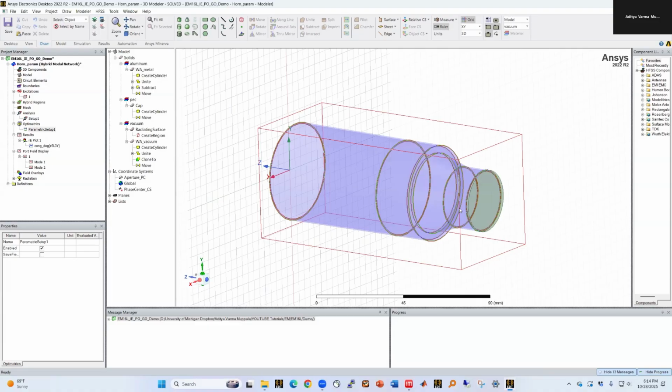And that's not that uncommon, that in two different cuts the phase center moves, because the phase front is not exactly spherical. It is somewhat elliptical, right? So it's like in one cut, it has a slightly different radius compared to the other cut. No, not slightly different radius, slightly different origin, I guess.